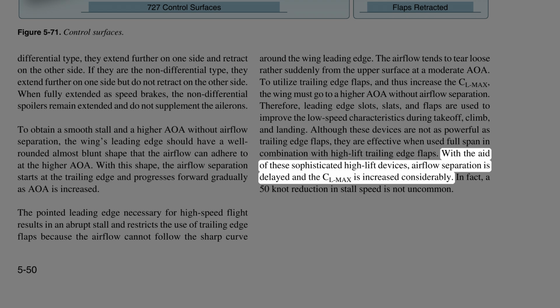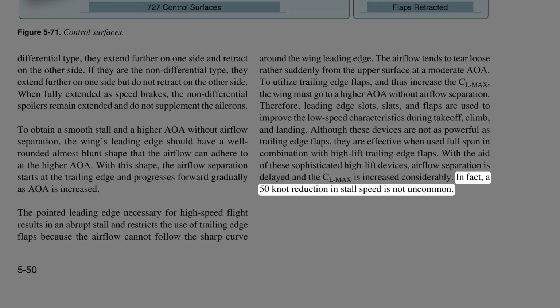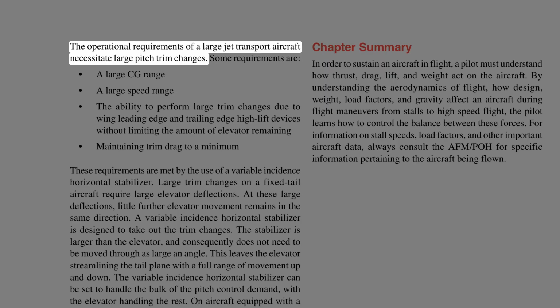With the aid of these sophisticated high lift devices, airflow separation is delayed and the CL max is increased considerably. In fact, a 50-knot reduction in stall speed is not uncommon. The operational requirements of a large jet transport aircraft necessitate large pitch trim changes.